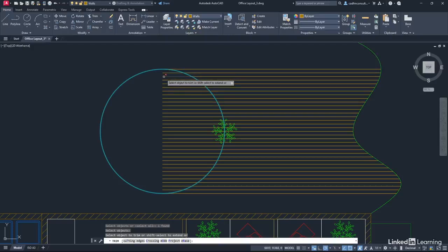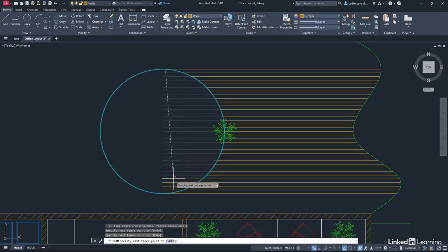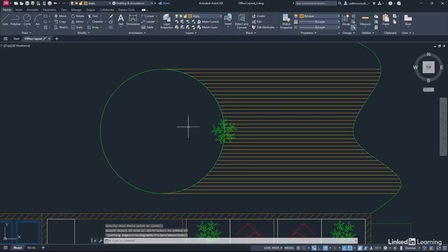You can do it individually. Can you see that? I can trim individually like we've done previously, but you want to place a fence like we did with extend earlier. So I get the pick box just there and left click. Drag it downwards and through all of the lines. Can you see? It's highlighting all of the lines to trim. Get it just down past that last one. Get the crosshair about there. Left click. As you can see, it's trimmed everything. Enter to finish. We've now got our nice circular landscaped area. And there's all our decking lines neatly trimmed and extended the way we want them to be.